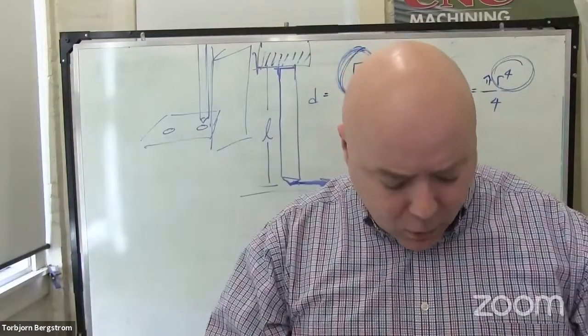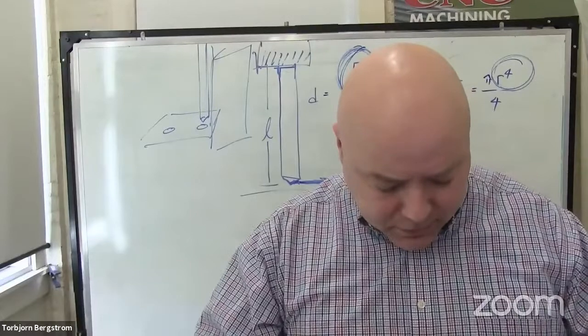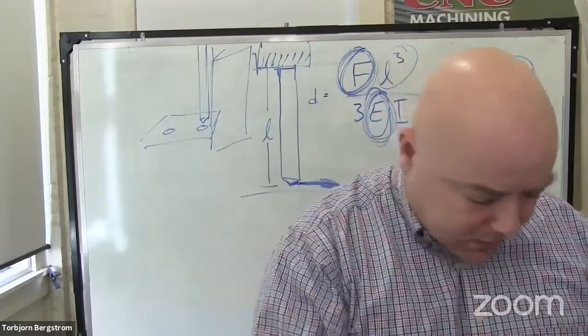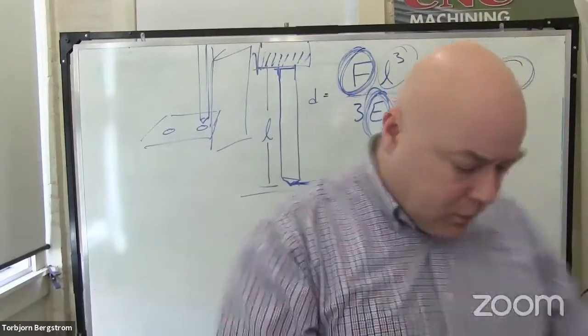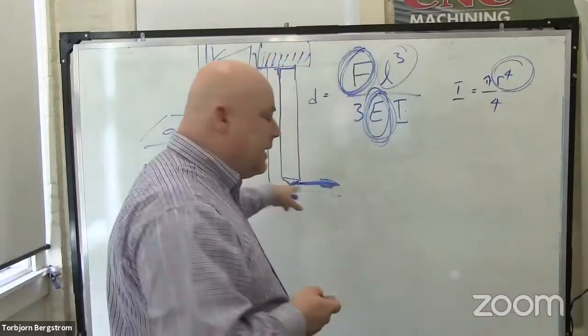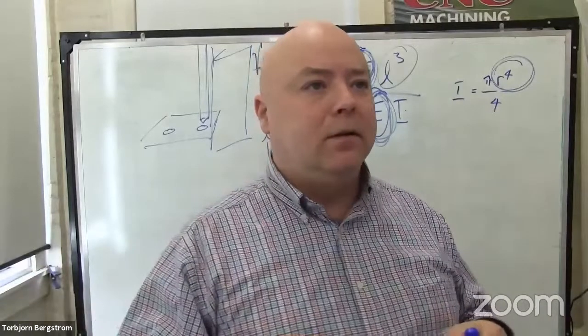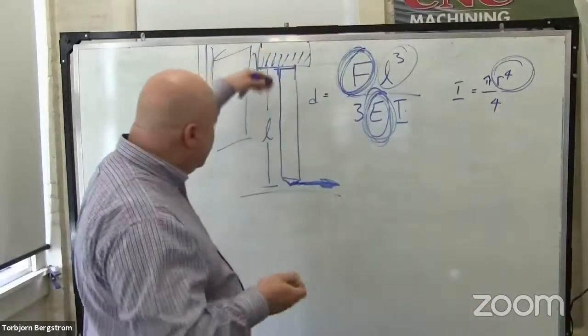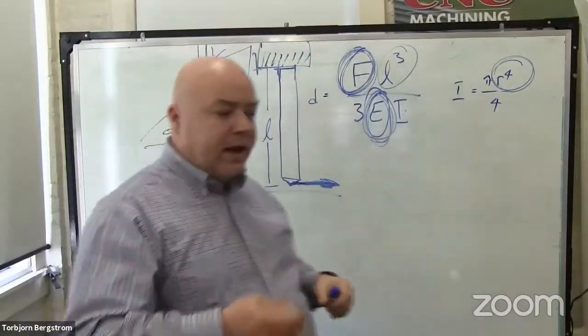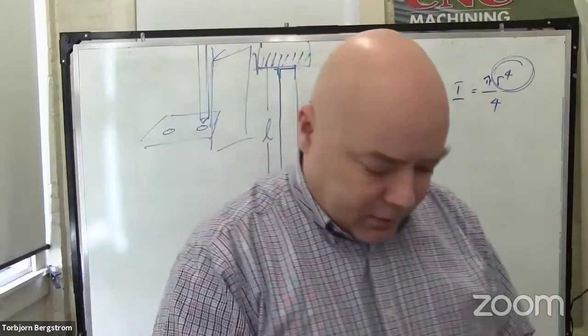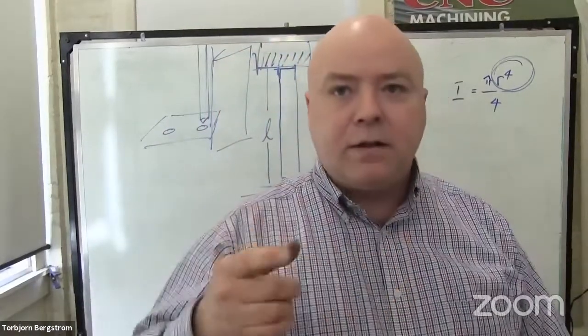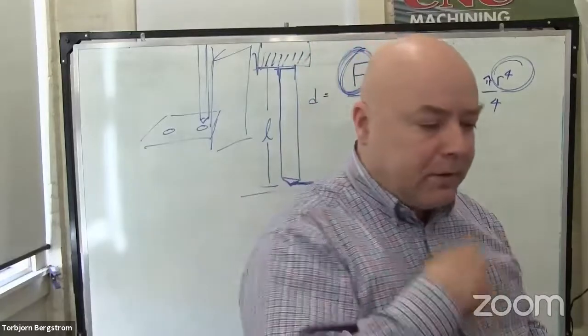If you need to make a hole with a large length to diameter ratio, you risk any little misalignment. Even with a spot drill, you could have a little bit of misalignment, right? Any misalignment, the deeper the hole goes and the skinnier the hole is, risks breaking the drill or having the hole come out in the wrong place.